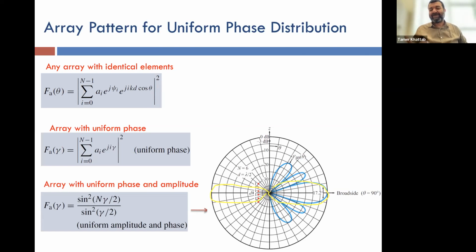Now you can see that using an array of antennas, we can achieve something which is almost impossible to achieve using a single antenna element. For example, here, we can make sure that the power is radiated only in one direction. It doesn't go in the other direction, right? And not only that, we can also get some side lobes. Sometimes these are desired, especially if they are not much smaller. If you look at some antenna designs, you will see that this might be desired so that you can communicate to two receivers at the same time, for example, okay?